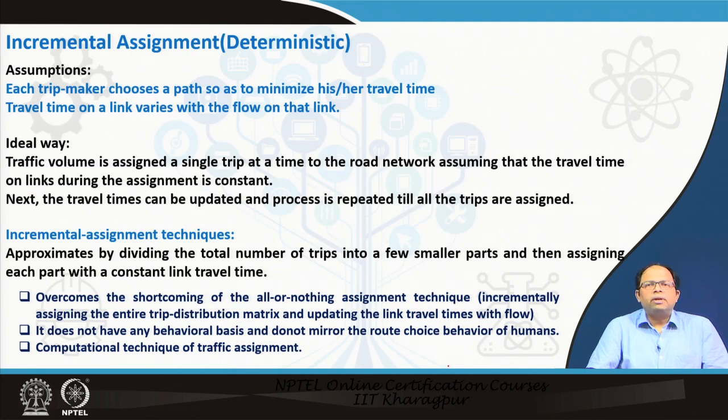So next we look into another technique which is called incremental assignment. This is also a deterministic technique. Now what this technique assumes is each trip maker chooses a path so as to minimize his or her travel time. This is basically following Wardrop's equilibrium, we have already discussed Wardrop's equilibrium. So this is following Wardrop's first equilibrium. So each trip maker chooses a path so as to minimize his or her travel time.